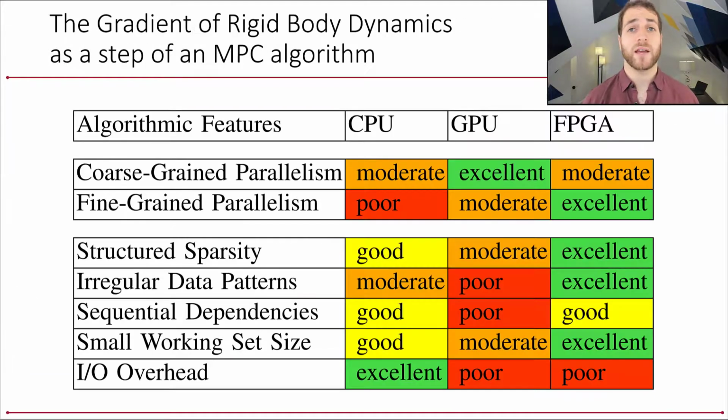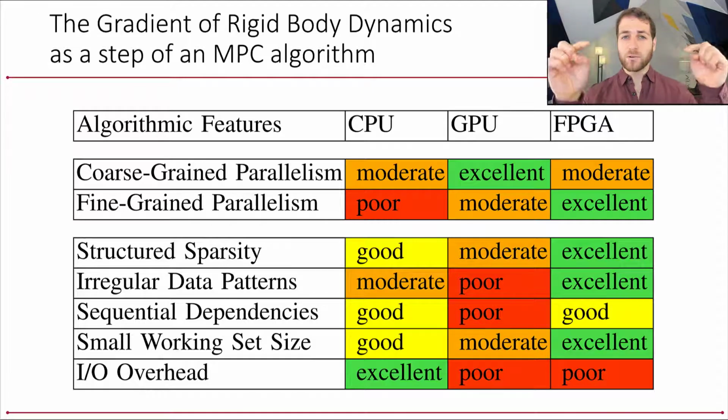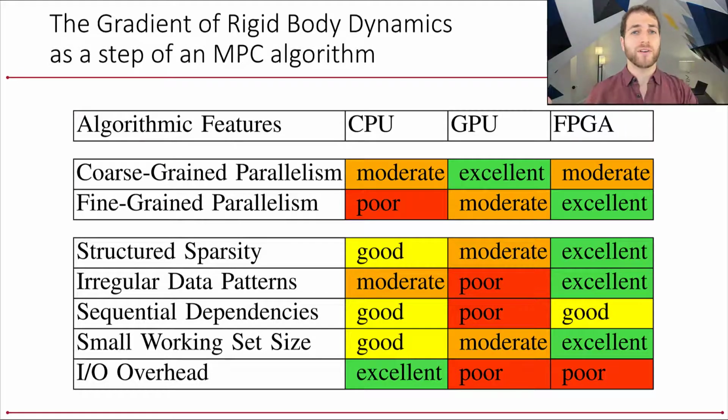The FPGA, on the other hand, is actually quite good at a lot of these irregular access patterns with small working sets, as we can create these custom functional units that can just directly encode these sorts of operations. Right? We can do a mux into a multiplication tree that makes sure we pull the right things from one vector and from another to quickly do a cross product really super rapidly.